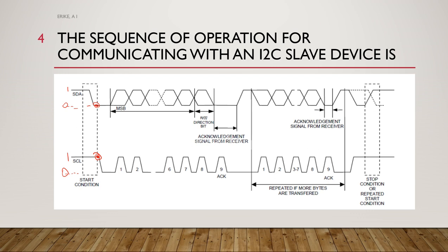Okay. So the master will now wait for the acknowledgement bit from the device upon byte transfer complete for a write operation. All right. So when the master finishes writing to the device, it will wait for the device to say, okay, you are done writing, for the write operation, and then it sends an acknowledge bit to the slave device for a read operation.